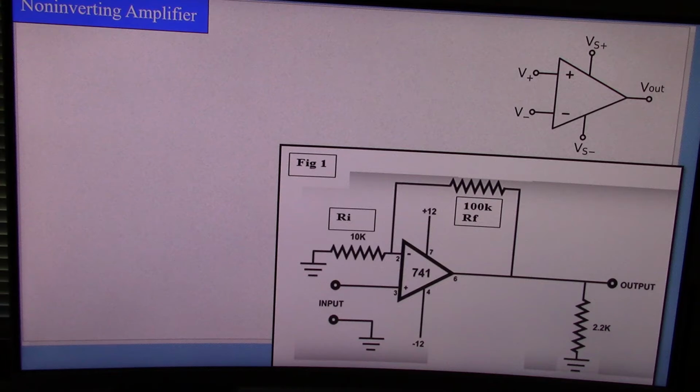I mean, it doesn't have to be. Most of the time these numbers are correct for a 741 series operational amplifier. This is the most common number of these, by the way, 741. And we are feeding it plus 12 volts and minus 12 volts. So can you just imagine, if this 2 input is bigger than this number, the output will go to negative 12 volts. If this 3 is bigger than 2, then the output will go to plus 12 volts.